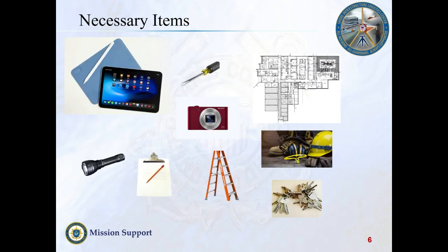There are several tools and materials you'll need to assist in the collection of this information. There will be a large amount of information to collect, and this can be done on a mobile device, tablet, or good old pencil and paper. A copy of the equipment enrollment form is a must to ensure you record all the required information for each piece of equipment. You'll also need a camera for taking pictures of equipment, the surrounding areas, and nameplates or other features. It is extremely helpful to bring reference documents such as facility drawings, maps, the maintenance requirements list, and/or previous asset lists, if known.